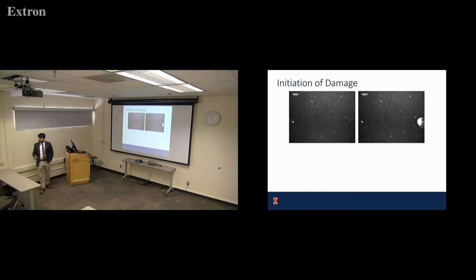Okay, so what about the initiation of damage? In this case, we wanted to say where are these cavities forming and why. What you notice is you've got this point here, and then once we apply some load and get up to peak, it actually forms a cavity right at that inclusion spot. So we thought that was very interesting. It forms at the inclusion, not in the matrix.